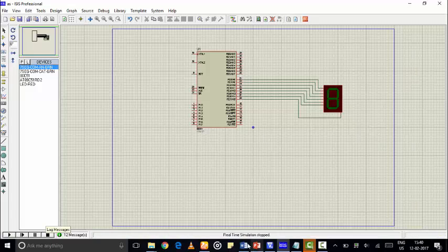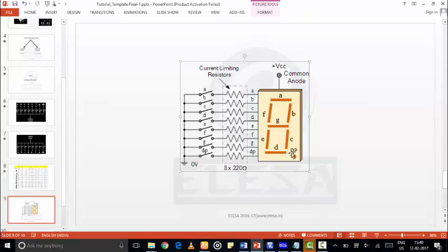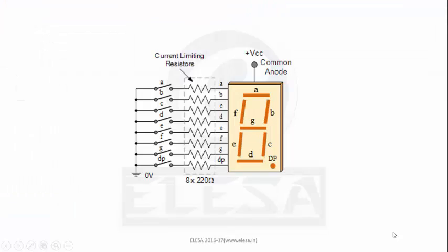Now that we are done with this simulation, there is one thing worth noting. All of this works perfectly in a simulation, but in real life, there is a major concern of overcurrent, which would never happen in case of a simulation, obviously. Although a 7-segment display can be thought of as a single display, it is still 7 individual LEDs within a single package, and as such, these LEDs need protection from overcurrent.